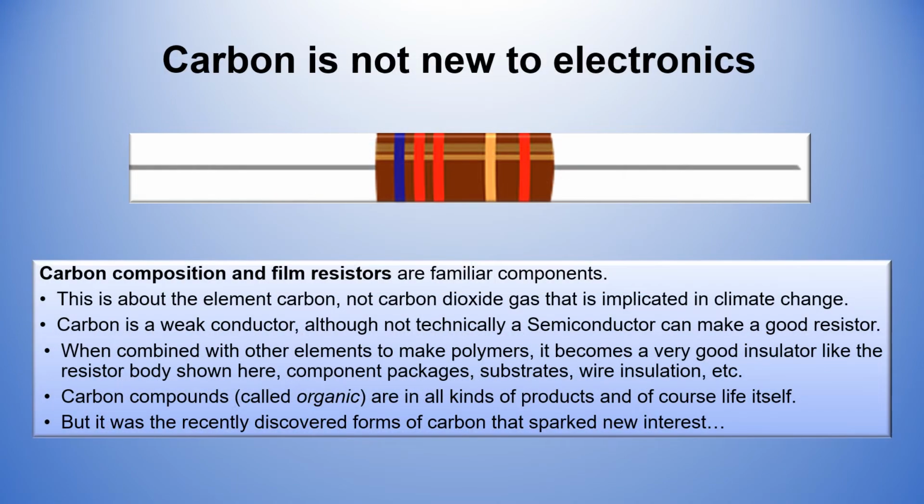Now, carbon is not new to electronics. You see a familiar axial resistor here. And think about the element carbon. It's not just carbon dioxide gas, which is implicated in climate change. It's the solid element, carbon itself. Carbon is a fairly weak conductor, not technically a semiconductor, as we usually think of them, but it's a good enough conductor and a poor enough conductor at the same time that it can make a very good resistor.